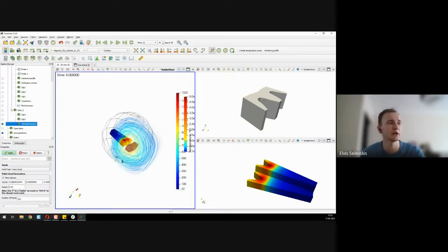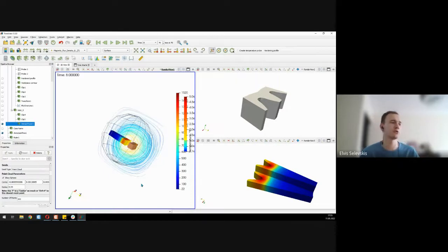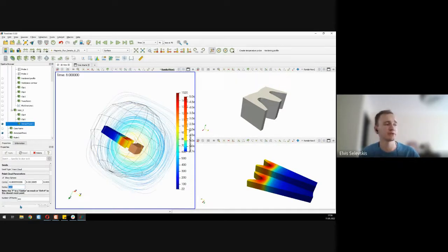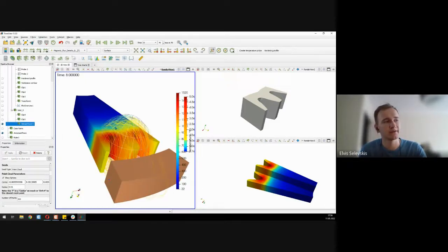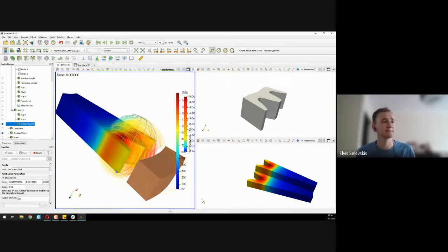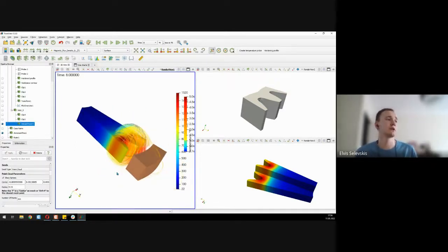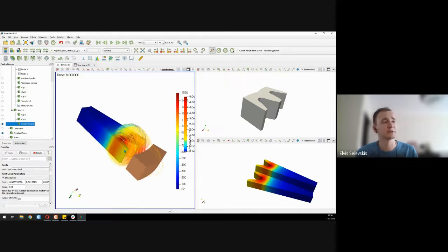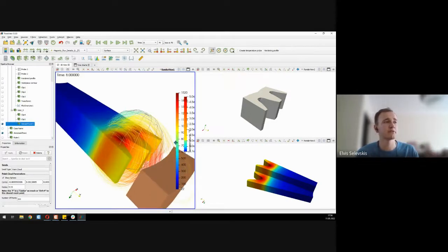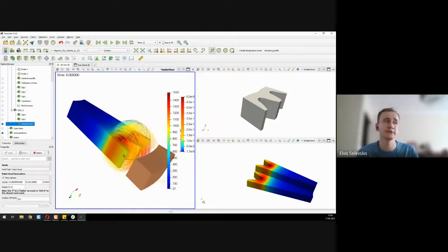Here you can see I have got the entire system which I'm interested in within this sphere, and that's pretty much an optimal size for it. If I make it too small, let's say change it to 5 times smaller, what you will see is the limitation that it puts all of these lines in a small sphere, and you don't really see the entire view of the magnetic field. These lines will be correct, but the strength of them is quite high here, and you don't see the whole picture.